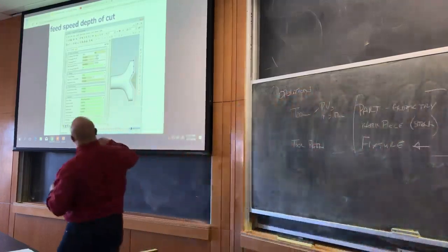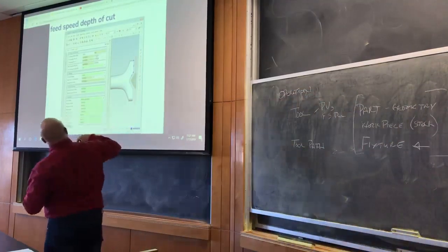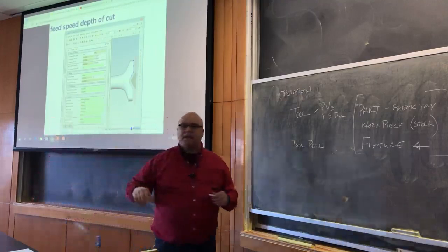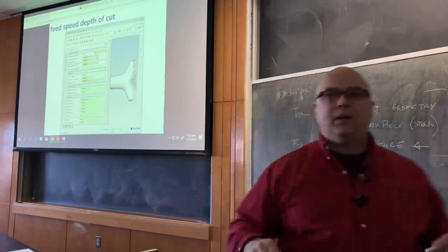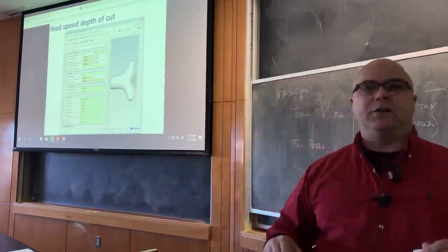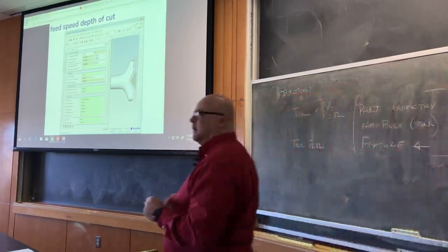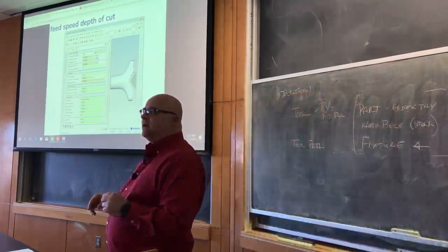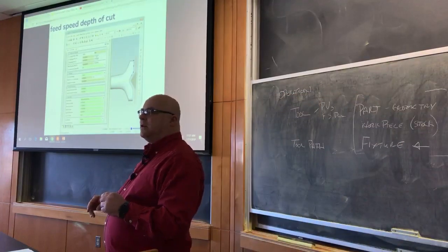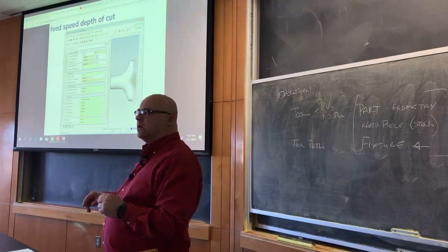Okay, so that's there. Now here I've got the X, Y, and the Z feed rate exactly the same. Is that what you learned in lab? That X, Y, and Z feed rate should be exactly the same for a tool like this? What did you learn in lab, Stephen? I think the XY figure is 0.003 and this is 0.006. Yeah, so is that like a quarter?